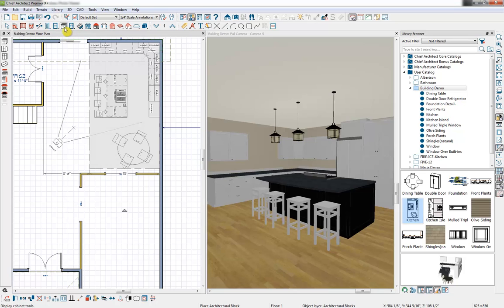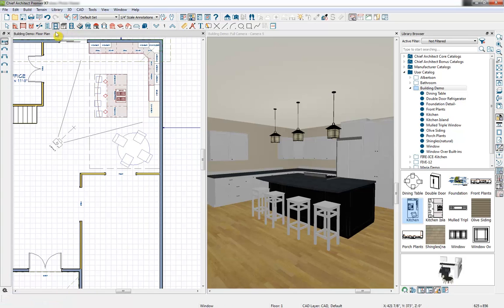And when we're in our view here, for the window, I'm going to place that right over our sink area, and that will automatically resize to fit over our cabinetry. So you don't have to do any additional steps to resize that. Another efficiency tool in Chief Architect software.